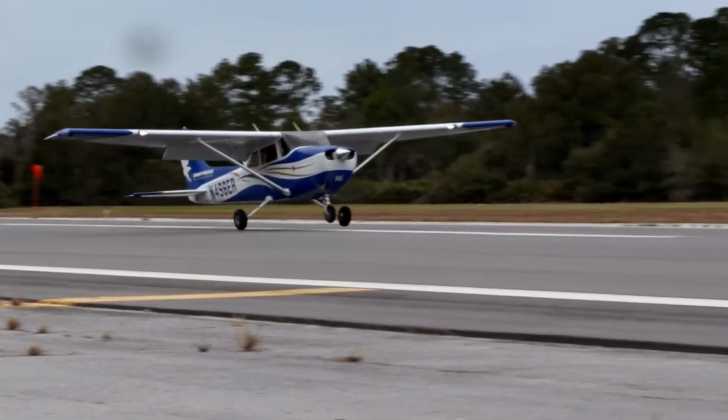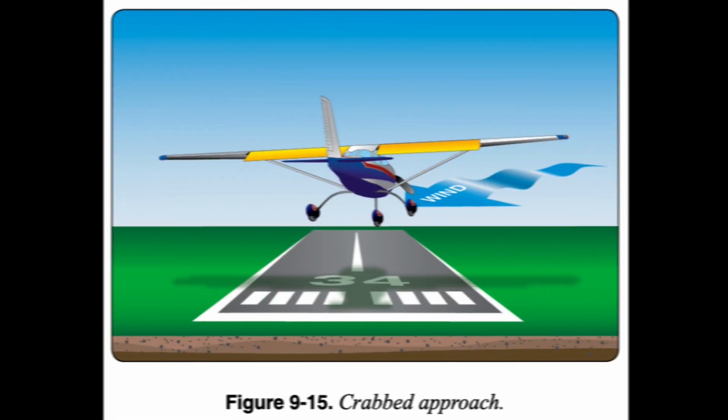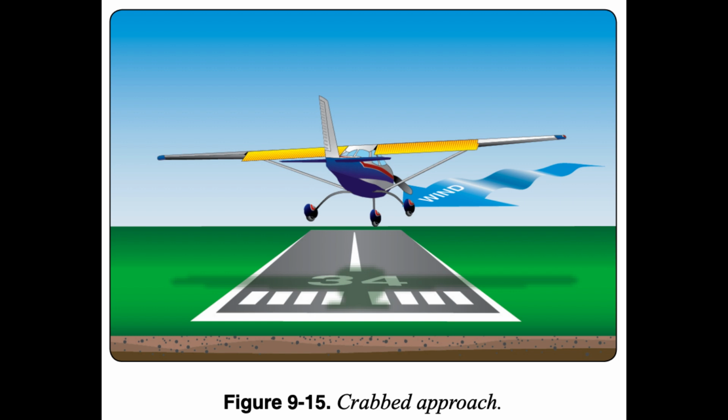Crosswind final approach. When using the crab method, the pilot makes a coordinated turn to establish a heading, crab, toward the wind. The selected heading should align the airplane's wings-level ground track with the center line of the runway. The pilot makes small heading corrections, if needed, to maintain alignment with the runway.